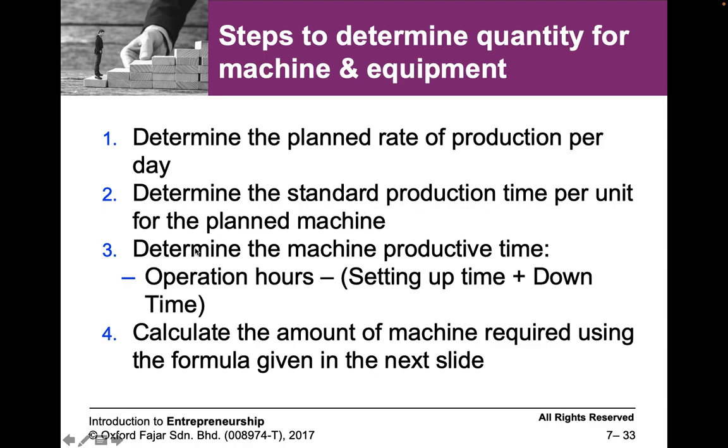And then determine the machine productive time. Okay, so how to determine the machine productive time? It starts from the company operation hours. Let's say your company is operating 8 hours. So 8 hours minus setting up time plus downtime.